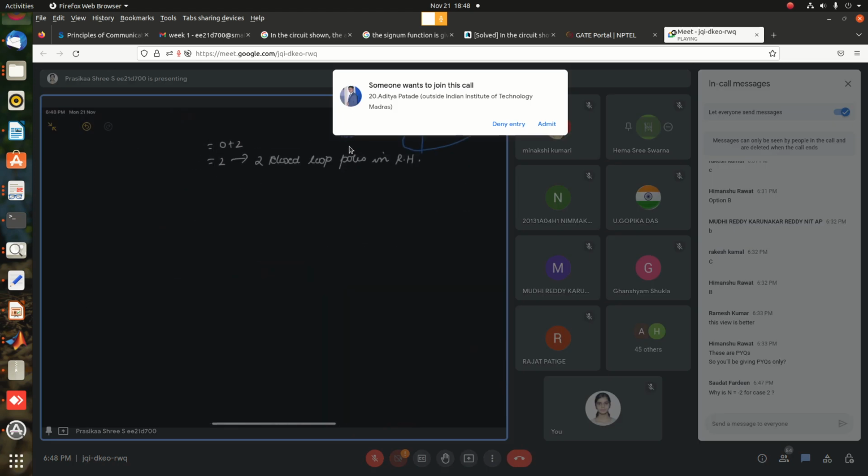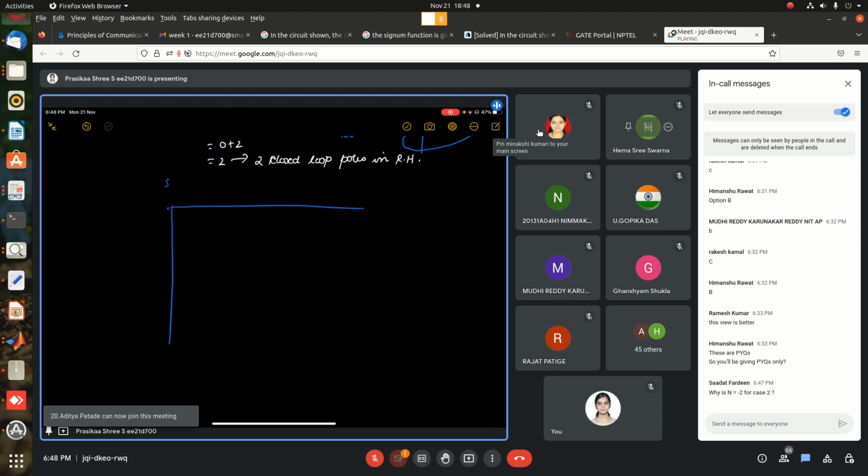So now our interest is to formulate the Routh array. How will you do that? It's quite simple. Suppose take it like this: s power 4 plus s cube plus s square plus s power 1 plus s power 0 is equal to 0. Any coefficients can be missing as well. So whenever you are given a polynomial like a s power 4 plus b s cube plus c s square plus d s plus e s power 0, there should not be any missing powers.